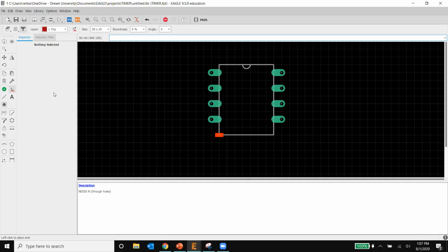Maybe you want to add an SMD. For SMDs, you can add them like this. So maybe 1, 2, 3, and 4. SMDs are usually more compact than through holes, and it's probably a better choice. But see how much space this is taking, see how much space this is taking. So it depends on what the component is. But if it's a custom component, you want it to have less space, which is a good thing.